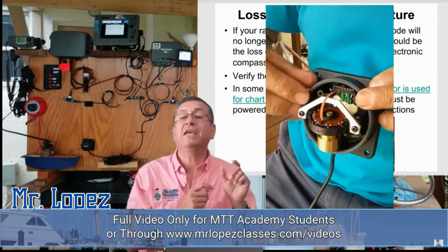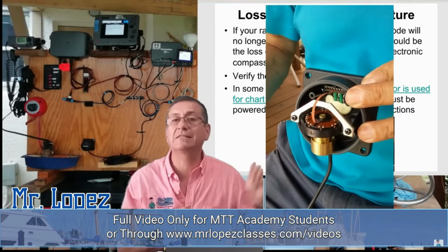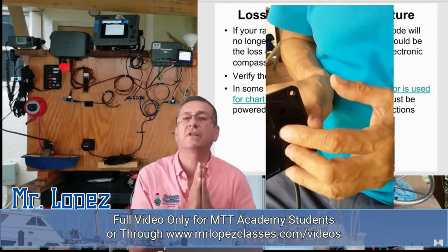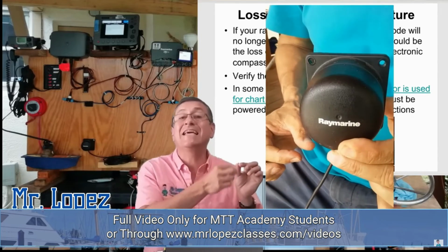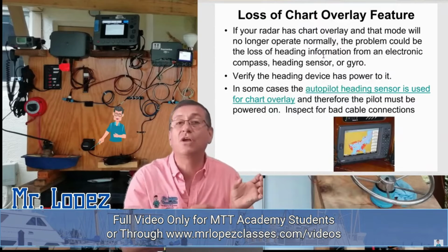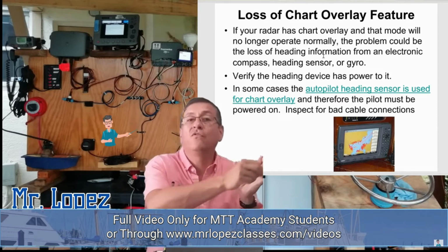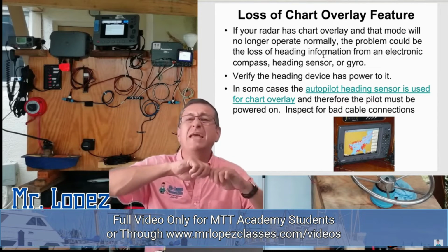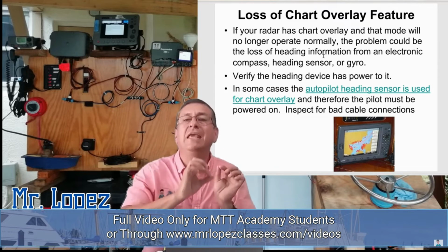Okay, close again. Be careful with the seal. That's the seal that you have on the screen right now, that gasket. Be careful with the seal. Put back the cover and verify that the sensor is in a vertical position. Follow the cable. Follow the cable between the sensor and the computer. Follow the cable and verify that it is not bent, not kinked, not broken, and is properly routed.